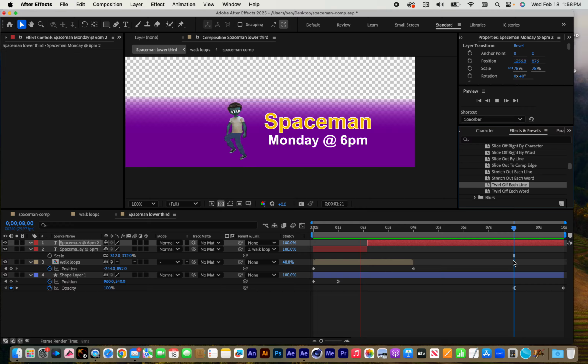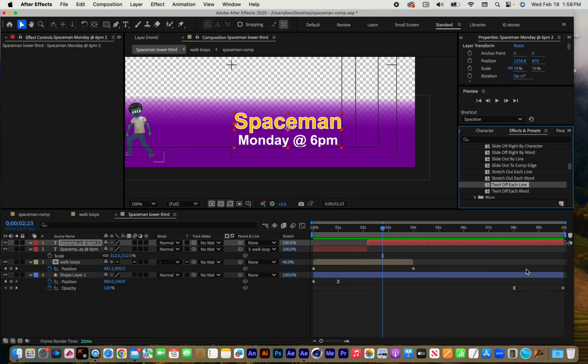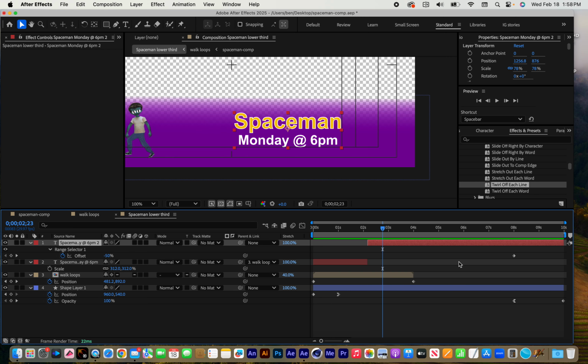Ooh, that was neat. And again, if I hit the U key to show the keyframes, select my layer, hit the U key, there we go. Now, one of my keyframes does happen to be off the right side of my timeline, because when you apply a preset, it applies the keyframes to the right of your time marker.